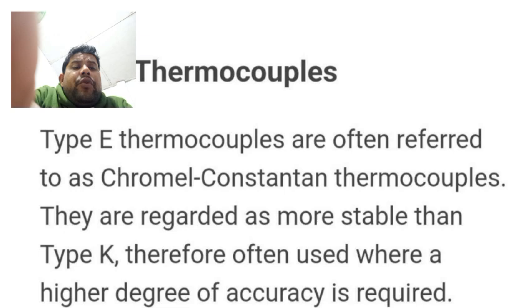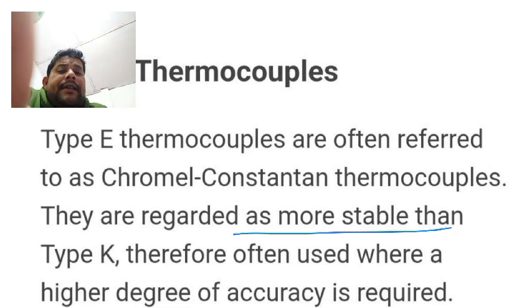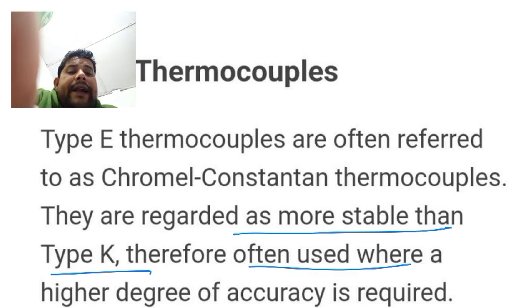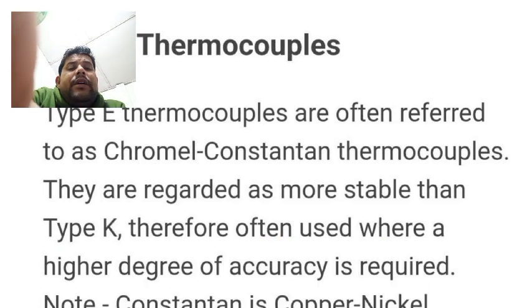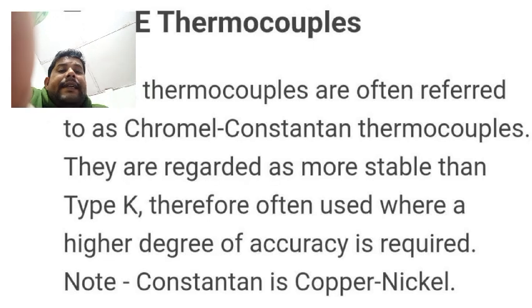They are more stable. Why are they important? They are more stable than the K-type. Therefore, they are often used where a higher degree of accuracy is required. Then we can use the E-type thermocouple.